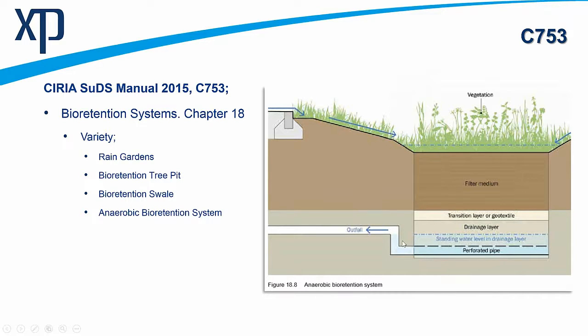There will be an outfall that's set at a slightly higher level, but maybe we're going to build in a pit or a sump with 300 millimeters or 600 millimeters depth of permanent water, such that the vegetation can survive through periods of drought and things like that. And possibly more important as we start feeling the effects of climate change in the future, for maybe longer, fingers crossed here, for a longer, hotter, dry spell as we get towards the end of spring and into the summer period of time. Maybe wishful thinking, but these are ways that we could start to mitigate against drought situations